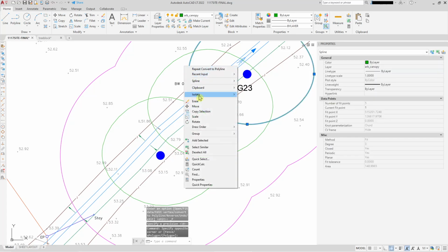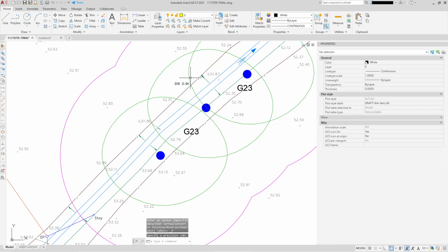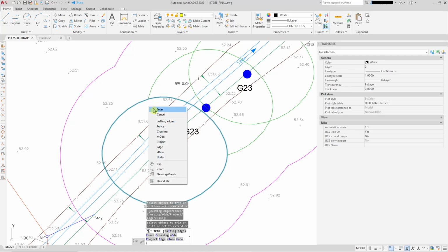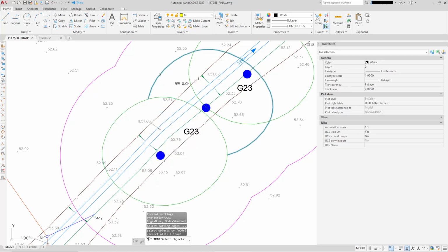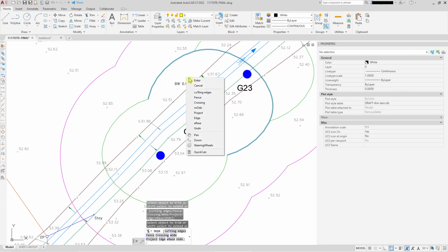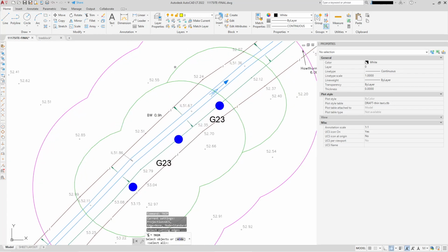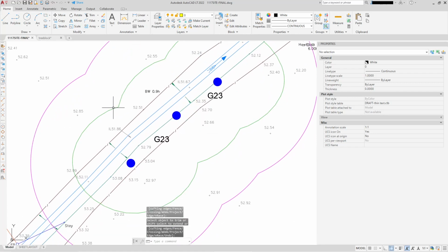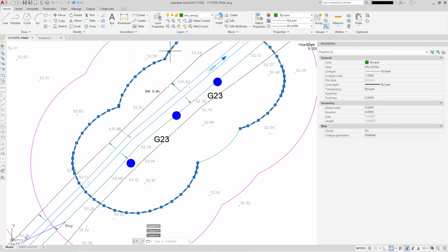If you already got polylines for canopies, then you don't have to do this. So now they're polylines, they're a bit chunkier, but that's fine. So now I can trim, select that one, remove that bit, select that one, remove that bit, and that bit, and remove that bit, and then join these together.